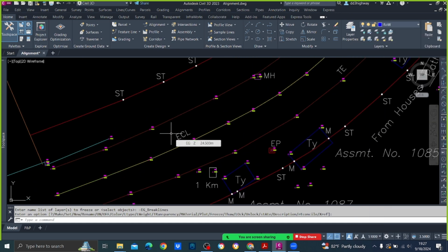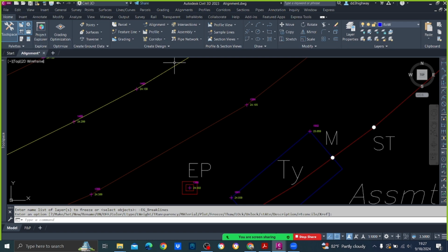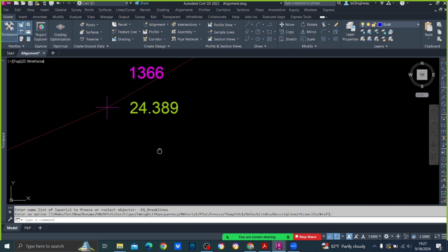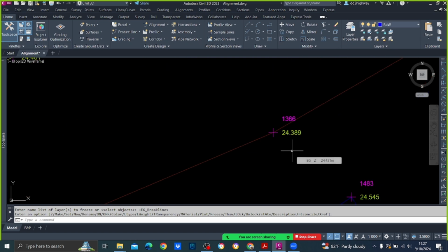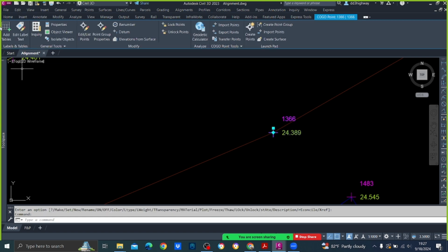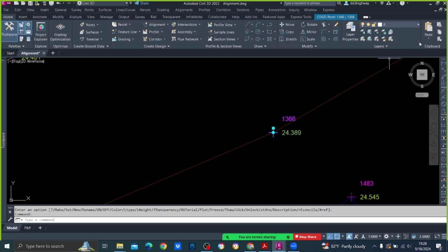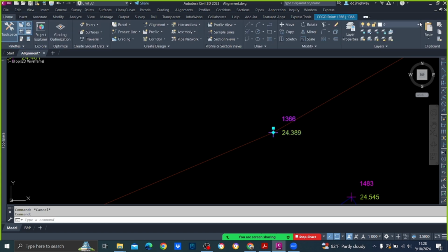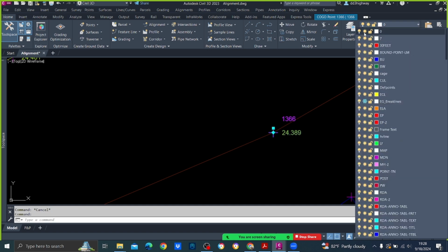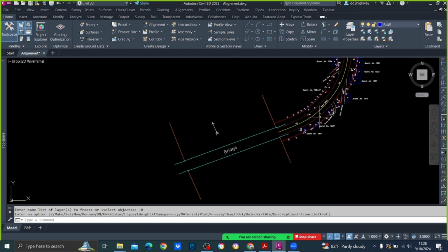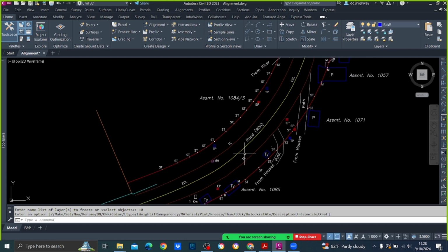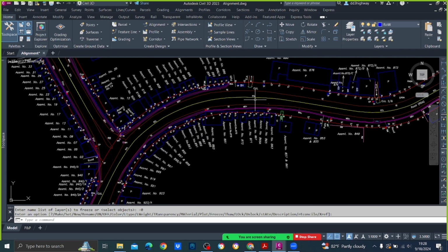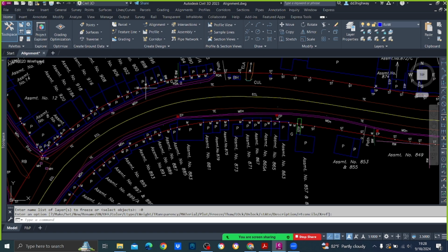All right. Now there's another thing. These points, we should not keep here. So we can switch off these points as well. Select that point. What is that one? 0. But you can't switch off this 0 layer. Just think, if you switch off the 0 layer, then everything is gone, right? Sometimes it is a bit difficult because the survey has done everything in the 0 layer.